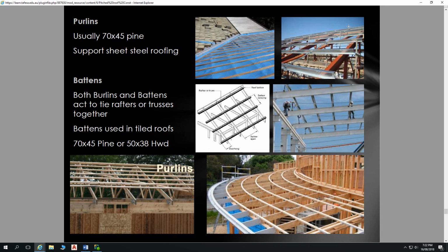Z purlins are really handy, mostly because they're easy to fix. They're easy to fix to the wall frames because, and I have to draw that. I'm trying to avoid drawing too much because the people at home watching this can't see it. But for this, it sort of really needs to happen. With our rafters, so our rafters go like that.